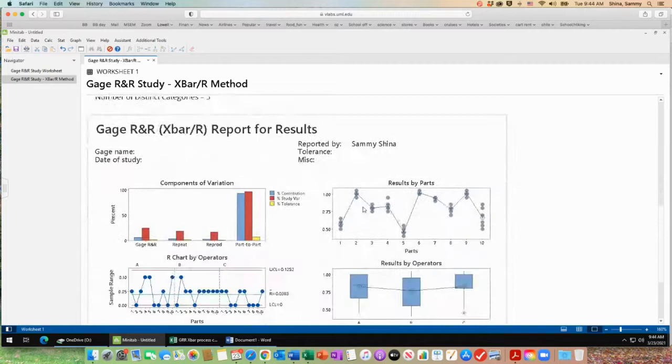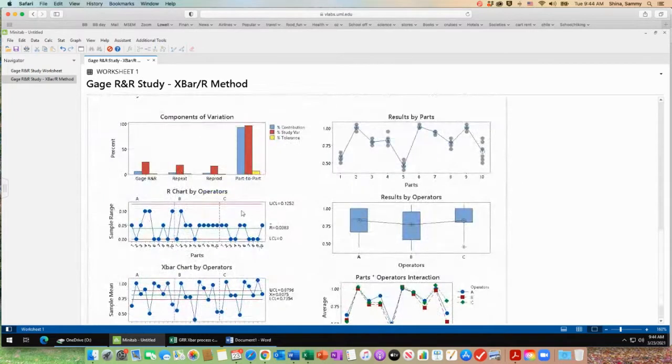Then there's these graphs, which I want to discuss with you very briefly for the GR&R method. What they do is they give you 3 colors, contribution of each component of variation. Okay, so that's the percentages that we did. Percentages of total variation, which is the thing we calculated, and then percentage of tolerance. Obviously, the percentage of tolerance is going to be small because the tolerance is wide. So the percentage of tolerance is yellow, which is very small, and these are the percentages. These are just a tabulation of the same percentages.